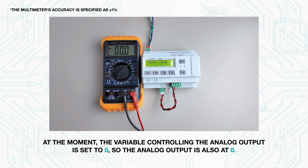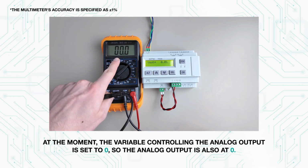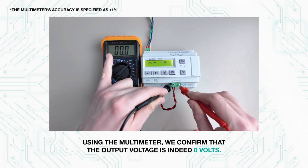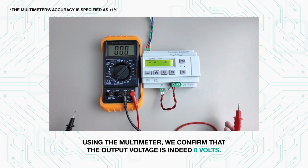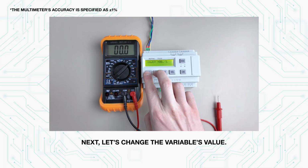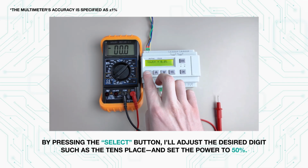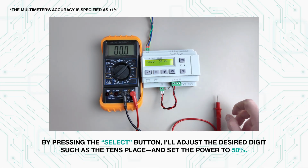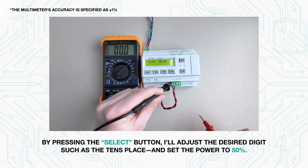At the moment, the variable controlling the analog output is set to 0, so the analog output is also at 0. Using the multimeter, we confirm that the output voltage is indeed 0 volts. Next, let's change the variable's value. By pressing the Select button, I'll adjust the desired digit, such as the tens place, and set the power to 50%.